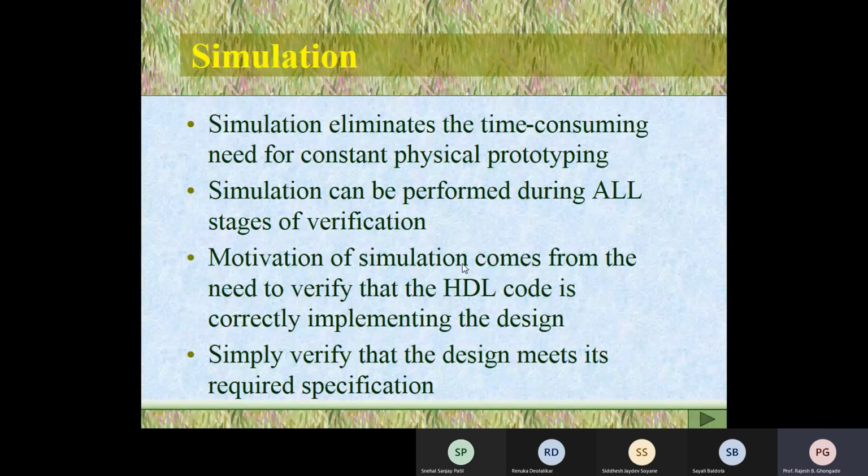Then is there a requirement of an IP level enclosure conforming to some IP standard, for example IP65? It is a standard for the enclosure for your entire system, so that decides your enclosure. So basically, you always start your design with specifications from the customer: input specifications, output specifications, and the ambient specifications.